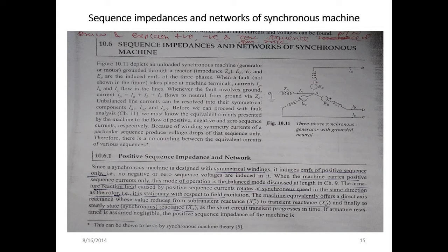Now, here we have to calculate the positive, negative and zero sequence components. First of all, we'll discuss the positive sequence component. But before that, keep in mind that we'll calculate the positive sequence component, represented for the three-phase system; since that system will be balanced, we can also show it on a single phase basis. So first, we'll consider the positive sequence network for the synchronous machine.